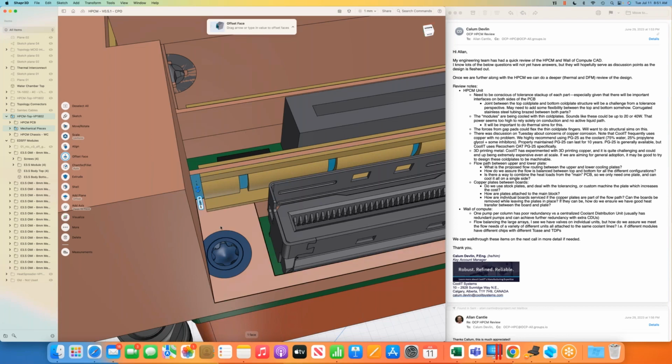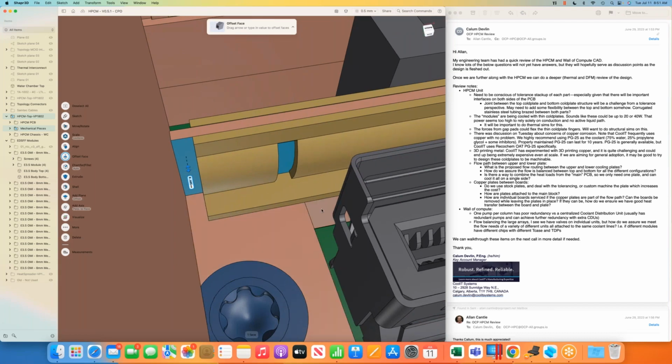Were you thinking of flow within that 1.6? No, there'll be no flow, but this will be part of the solid block that this gets made out of. However we make it, the water will flow below it here, in this area. This is a fatter piece. You see, this is 4.5 millimeters, which would be 5.5. So the water would flow in the fatter piece below, but it would all be part of the same mold, or whatever you want to call this copper block. So you have a good copper connection, a good thermal connection, down to where the water is flowing. That was the reason for this.